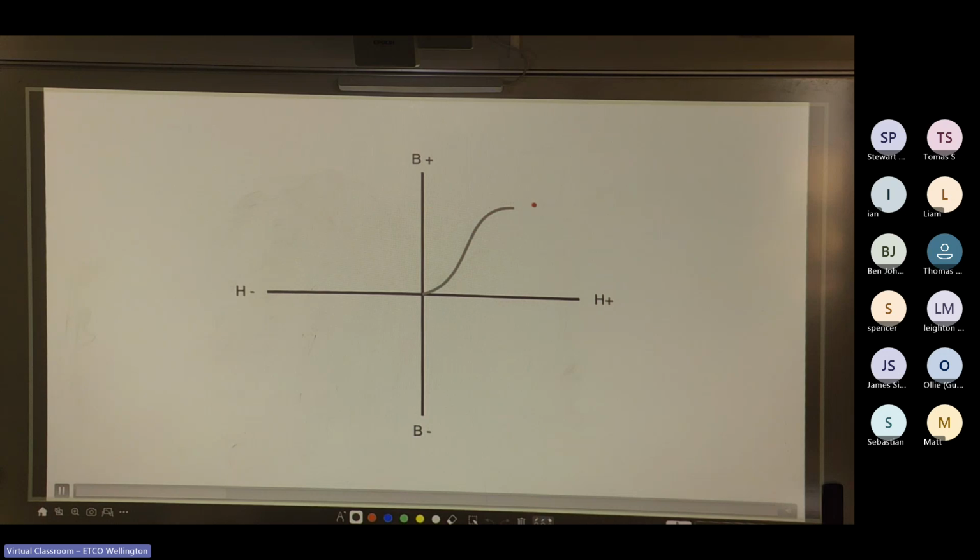And that point is called our point of saturation, which means that no matter how much magnetizing force you put on this, and keep increasing it, you can't put any more flux lines into that piece of metal. It's like putting toothpicks into the little toothpick bottle: it gets to a point where it's all full. And so we hit saturation. So we're going to see what happens when we do that. We magnetize it, and then if we get rid of our magnetizing force, let's see what happens.